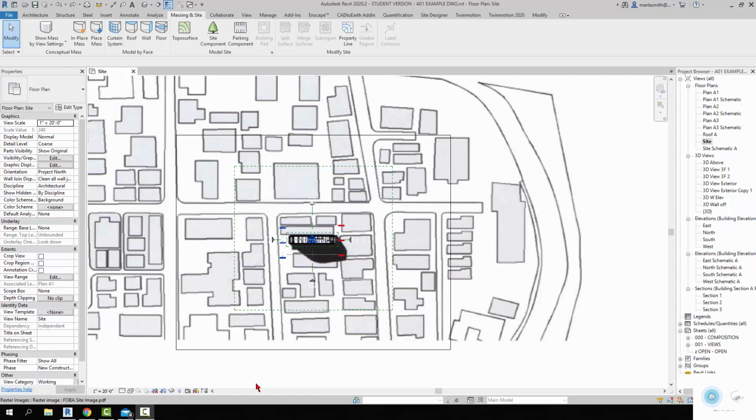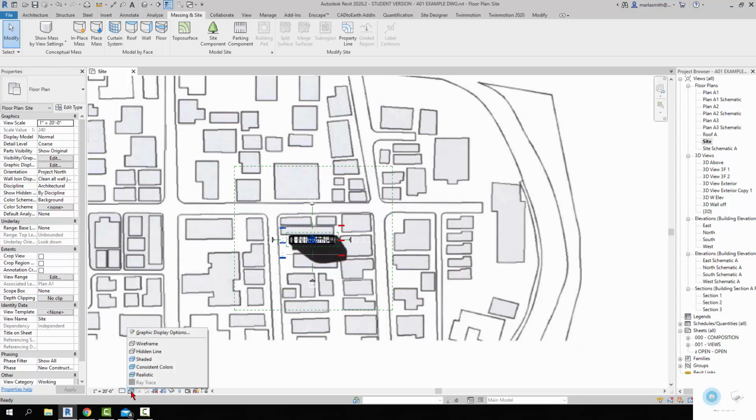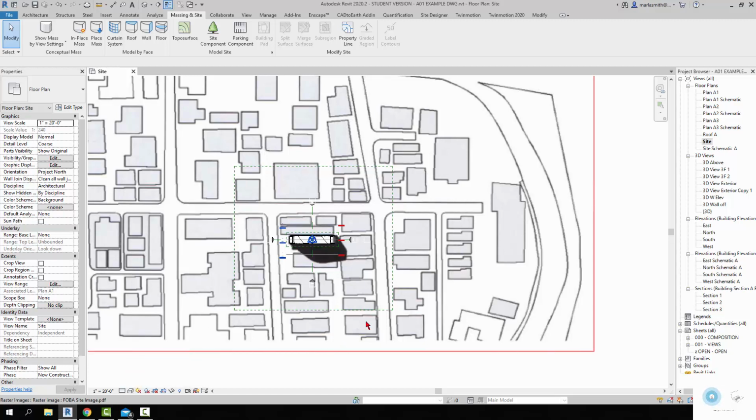Alright, we have our building in here and the image we want to use to create sort of a flat urban topography and some roads in here. So I want to go ahead and do that. First thing I'm going to do is just delete this floor that's in here. So I have a background, and then change this guy to a hidden line so we're not in wireframe, since we don't have anything to cover that, to hide this guy.